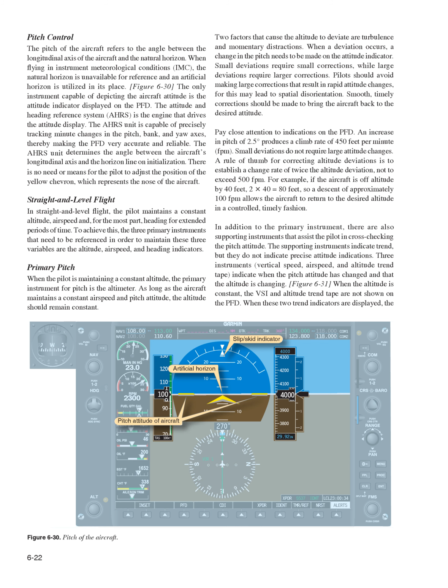Pilots should avoid making large corrections that result in rapid attitude changes, for this may lead to spatial disorientation. Smooth, timely corrections should be made to bring the aircraft back to the desired attitude. Pay close attention to indications on the PFD. An increase in pitch of 2.5 degrees produces a climb rate of 450 feet per minute, FPM.